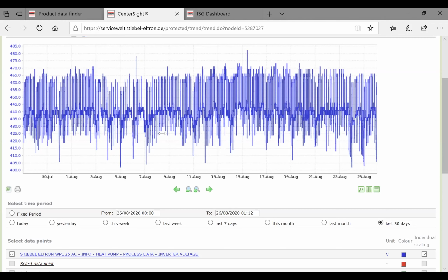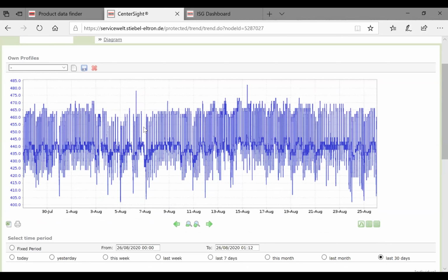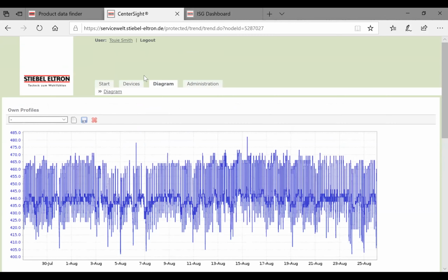Quite interesting. Now, if you're having problems with jobs out in the countryside and bits and pieces, this is where we would be looking first, to actually see the voltage, and you can actually get real historical data, and then we can look at where the faults may have occurred. We can overlay them with the voltage, and we can say, all right, we've had fault X, and we can see at exactly the same time we had a voltage spike of 483 volts. Makes for some very compelling data, and if an energy company or something needs to be taken to task, this information will be provided.